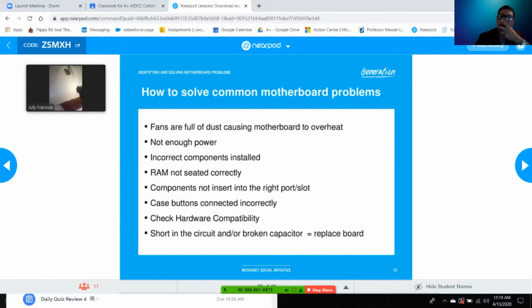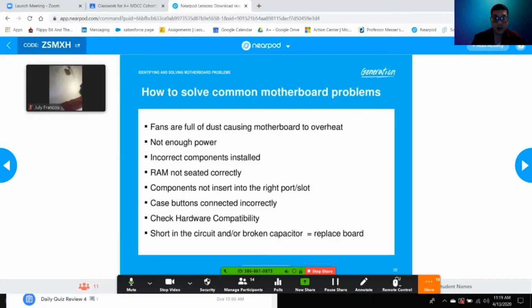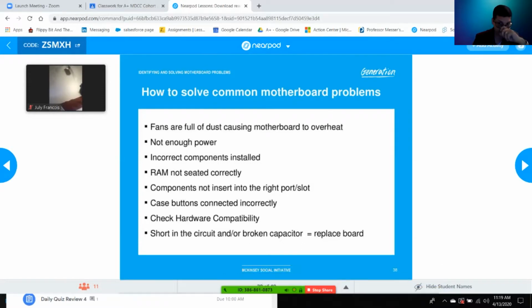Now you can see there are many different issues that a computer, or motherboard in this case, can give us. And if we're part of the issue ourselves, not seating the RAM correctly, you'll hear that famous beep. A little Morse code is going to start, letting you know. Depending on the motherboard, it has different beep sequences, right? It will use short and long beeps to let you know. Since it can't physically show it on the screen, it will beep, letting you know exactly what the POST sees as a problem. Thank you, Julie.